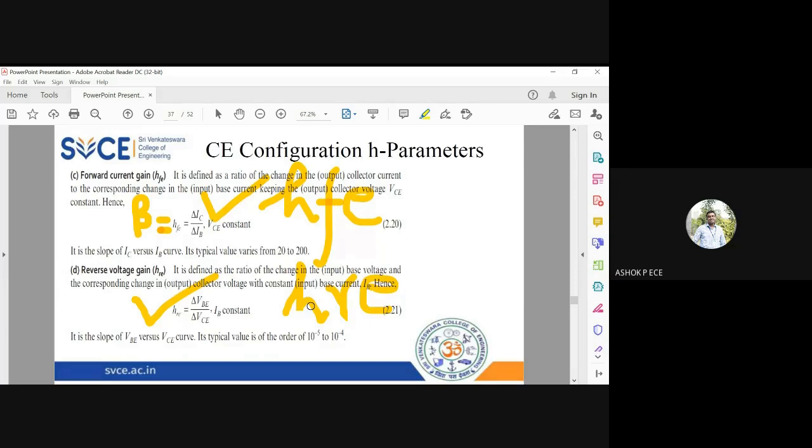See, when there is both current gain and voltage gain, what gain will also be there in an amplifier? Can somebody answer this question? In common emitter amplifier, I told you there is current gain as well as voltage gain. So if both are there, what gain will also be there in that amplifier? If current is multiplied, voltage is multiplied, what also will be multiplied? What is the other parameter relating current and voltage? Power. Power, very good. So this common emitter configuration will amplify your power also.